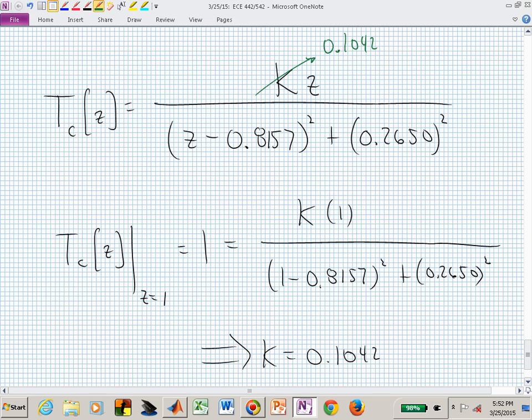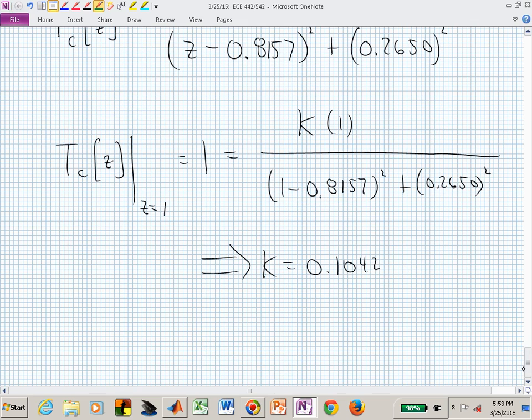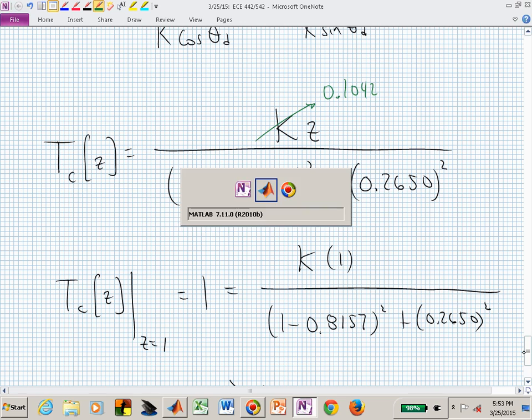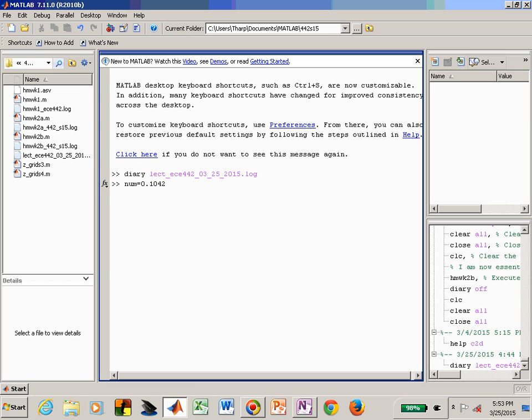And to obtain a 0 at the origin, what do I need to put into my numerator expression now that I have the gain inserted? Do you remember? So now I need to say something like 1 comma 0. Does that look okay? Now I have 1 times Z plus 0 times 1. That's going to give me a Z in the numerator, and that's what I want. This is now the numerator expression that I want.